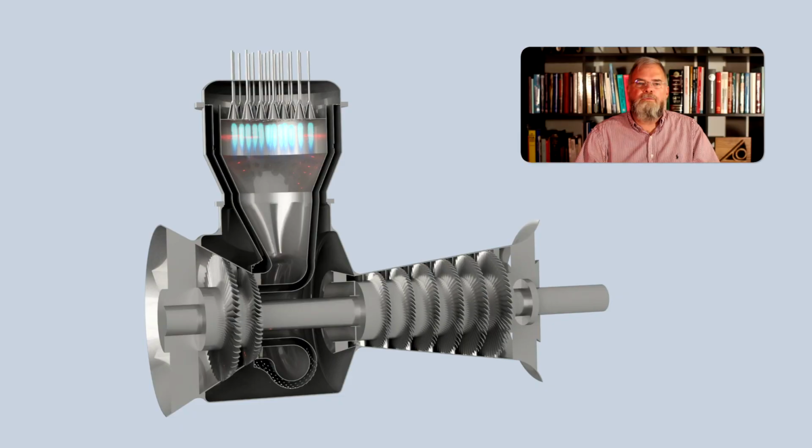In silo combustors, one approach to deal with this, which was the approach adopted by Brown-Boveri, is to introduce a large number of small premixed burners. As power is reduced, burners are switched off, cutting off the fuel supply to these burners, allowing the remaining burners to operate at a higher mean equivalence ratio farther from the lean blow-off limit.